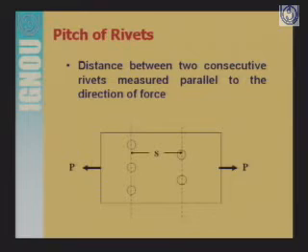One important terminology that is used in riveting is pitch of rivets. Pitch of rivets, as you see in this figure, is the distance between two consecutive rivets measured parallel to the direction of force. Here this thing is very important, direction of the force. Here this is one connection shown to you.